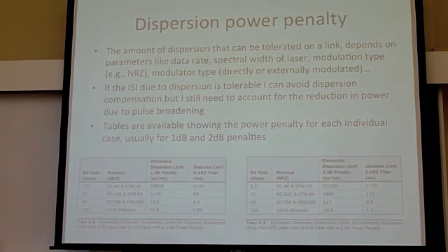What happens is, when you go over 2 dB, the ISI gets too bad. So basically, it's not worth putting in any more power. But these are examples. This is your bit rate: 2.5, 10, 40, 100 gig. This is the protocol. So this is SONET, this is Ethernet, that is NRZ, non-return to zero.